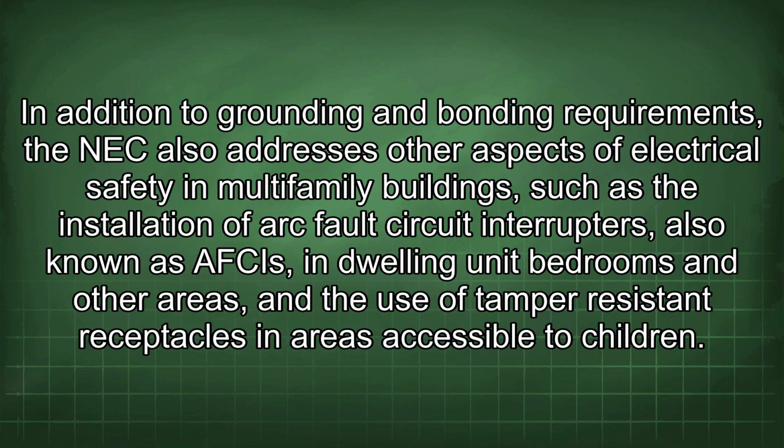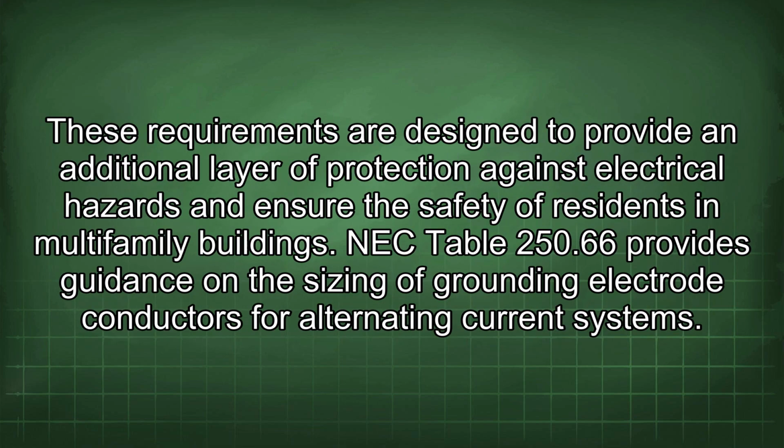In addition to grounding and bonding requirements, the NEC also addresses other aspects of electrical safety in multifamily buildings, such as the installation of arc fault circuit interrupters, also known as AFCIs, in dwelling unit bedrooms and other areas, and the use of tamper-resistant receptacles in areas accessible to children. These requirements are designed to provide an additional layer of protection against electrical hazards and ensure the safety of residents in multifamily buildings.